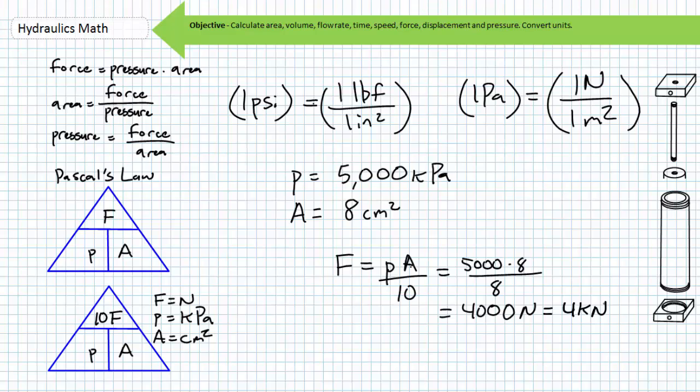This is tricky, and I don't like it any more than you, but rest assured, I'd much rather keep track of the number 10 than any archaic holdover from an agrarian society like gallons, acres, furlongs, firkins, or fortnights. You'd also get the same answer if you directly converted pressure to pascals and area to square meters, but I find throwing an extra 10 in our Pascal's law relationship is a lot easier because it accomplishes the same task